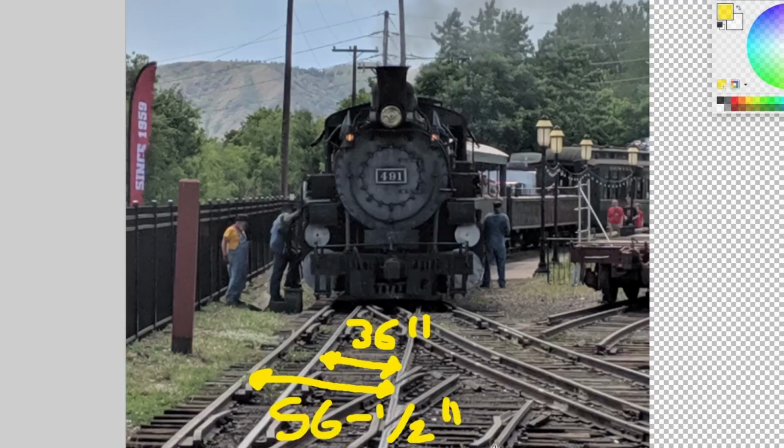Now, that's not always the case, though. Like anything in engineering terms, there's what we call a tolerance on the gauge, because you can't always keep it bullet perfect 36 inches or 56.5 inches. The trains are going to do stuff, the rail can bend, the rail can move, the ties can wear out, the spikes can get loose, all sorts of stuff, but we still need to run trains. So there's actually tolerances on this, and the specific tolerance of what is acceptable is entirely dependent on how fast you can run the train and the types of curves and everything, but 36 is what you shoot for.